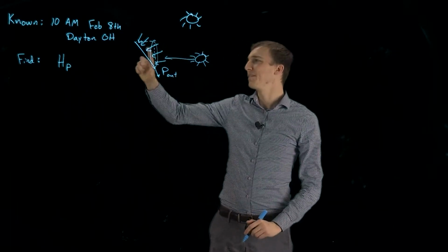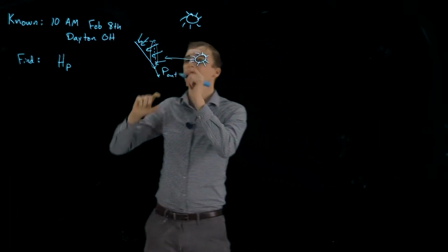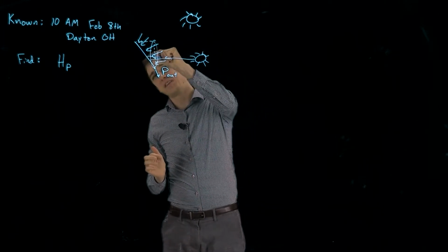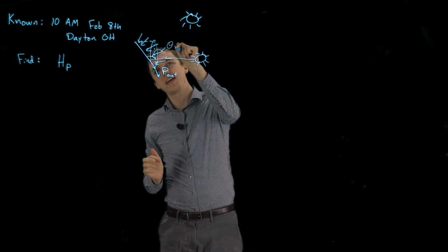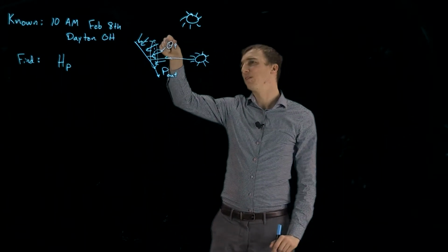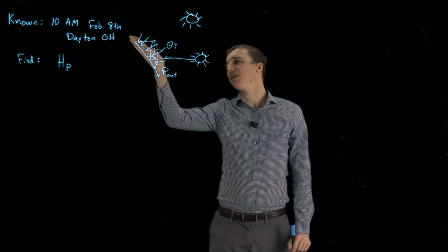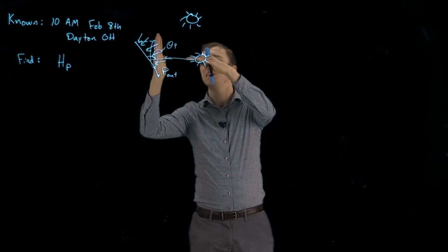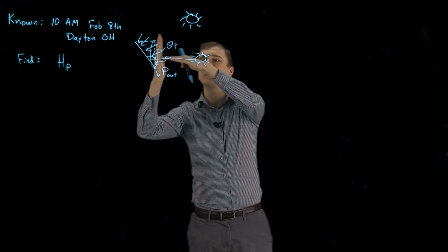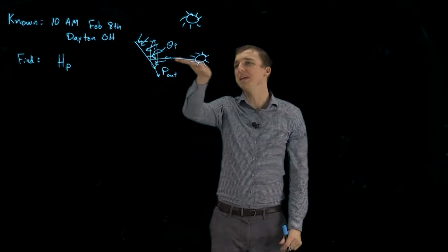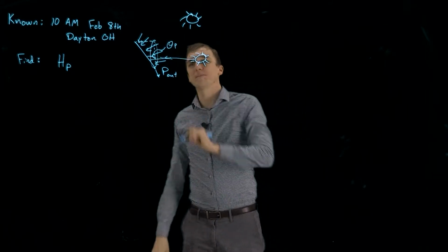So in this problem we are going to find the angle between the sun and the normal of the panel, theta p. If we multiply the area of the panel by the cosine of theta p, it projects the panel so that its area is normal to the direction of transfer of the beam, the direct transfer from the sun.